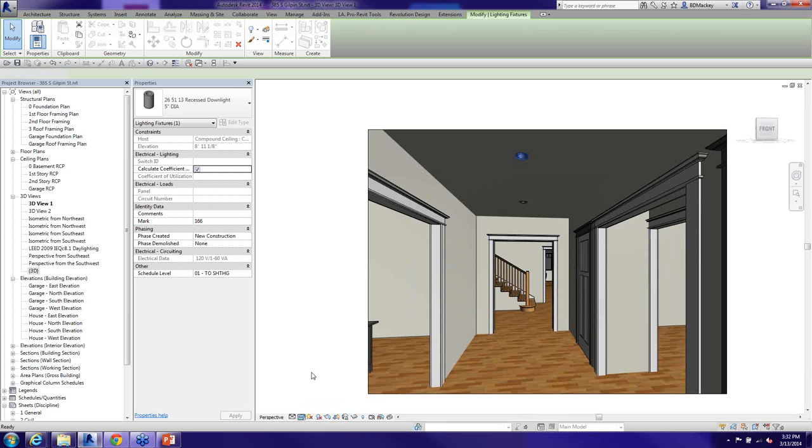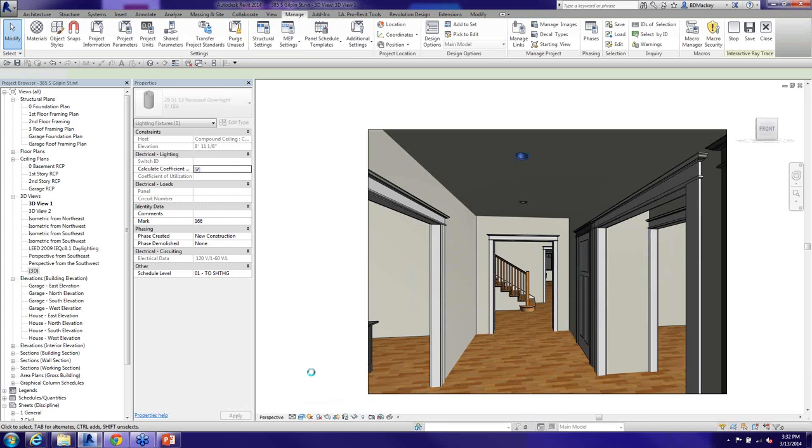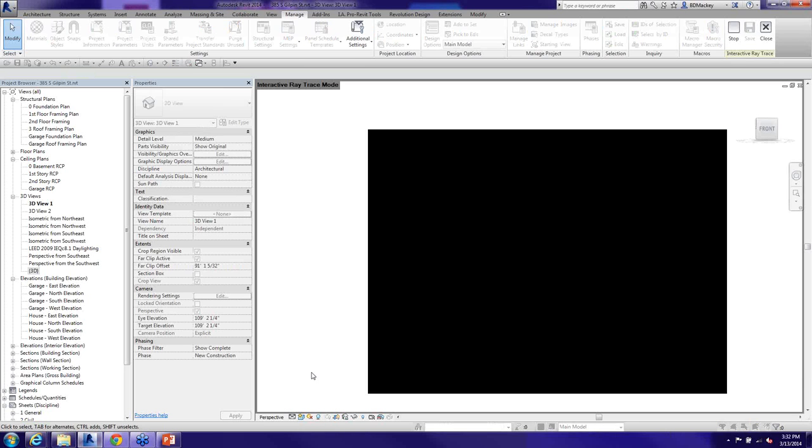If you really want to pick up on lighting, you can hit the little ray trace button, and Revit is then theoretically going to try to figure out how the light's bouncing around. This is one of my quick ways before I spend a ton of time hitting the render button. Let me just hit the ray trace, wait a minute or two depending on the complication of your view, and see what's going on. My laptop's about 3-4 years old now. It's not the fastest laptop ever, but it will take a while.